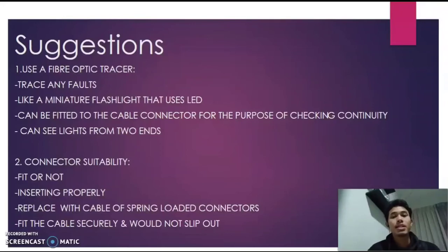Next is connector suitability. Before you use the fiber cable, you should check each of the connectors to see if they are well fitted or not. If not, it is necessary for you to rectify it by inserting them properly. If the issue still happens, you can replace the cable with a cable of spring-loaded connectors. In that way, connectors would fit in the cable securely and would not slip out.